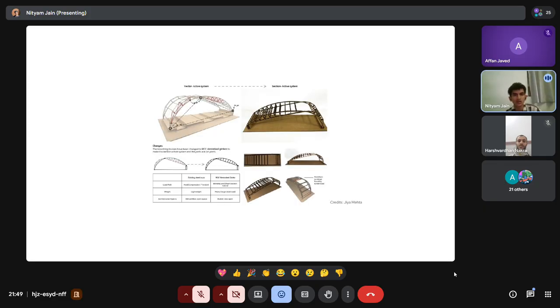Like someone can decide to make a steel building into a concrete building. That will change the thickness, the spatial qualities, the details of it, of how the joints will be, how thick will it be. So the whole expression of the space changes, but still keeping in mind the span, what is the function of the space, like extra columns shouldn't be there, that much span should be possible.